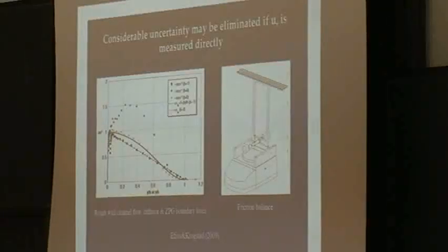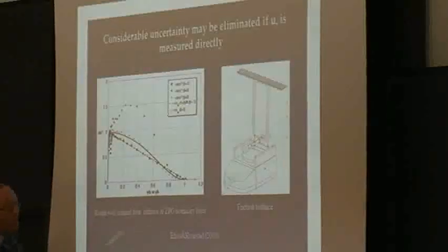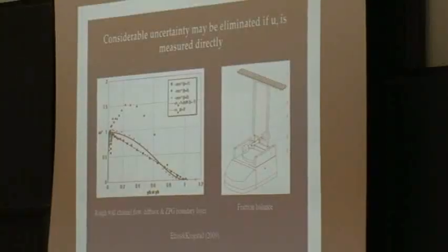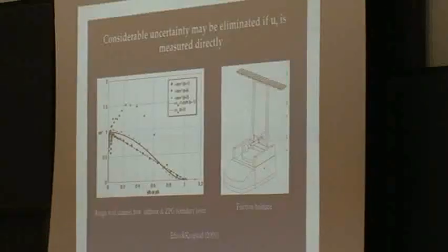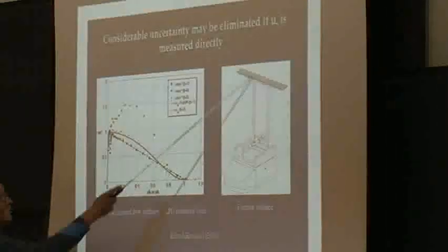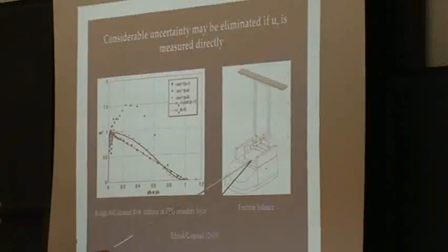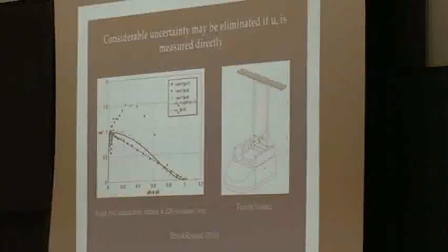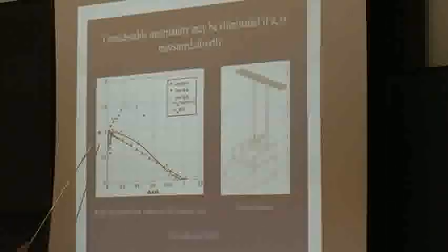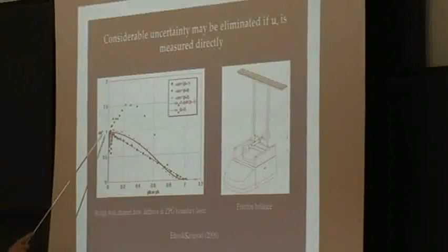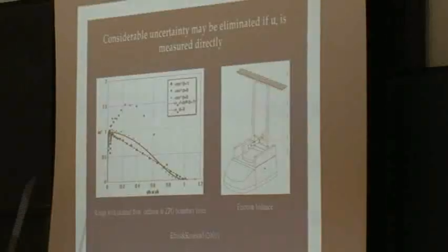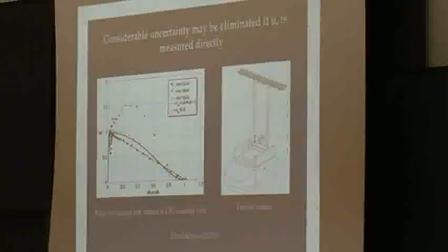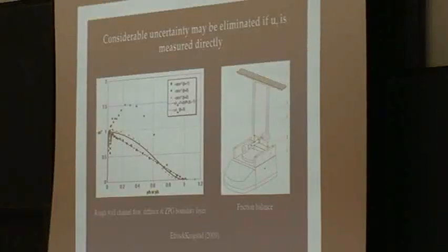Compared to the force that we're measuring up here, it gives us a resolution of about 10 to the minus 4, a rather accurate measurement. So we measure the force on this one by transferring the force down onto the balance. And then I'll compare that to what we measure of shear stress in 3 different rough wall configurations.